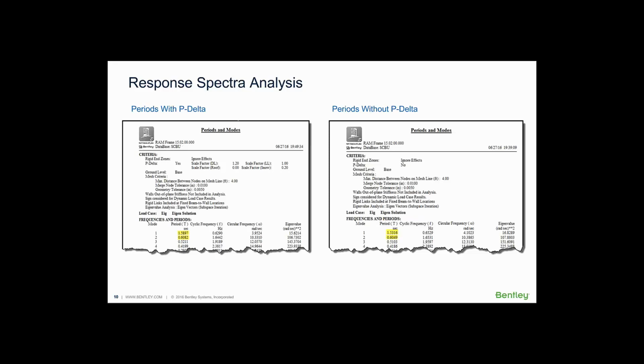Somebody did make the comment that for large structures with thousands of elements, the B2 factor looks very painful, and yes, it can be. Although I think in most cases you can calculate a B2 factor for a story and then apply it to all the members on that story, at least for a building. For something more exotic than a building, it would become more difficult.